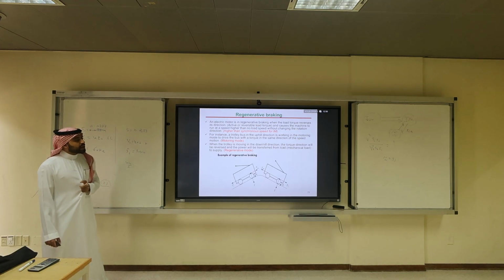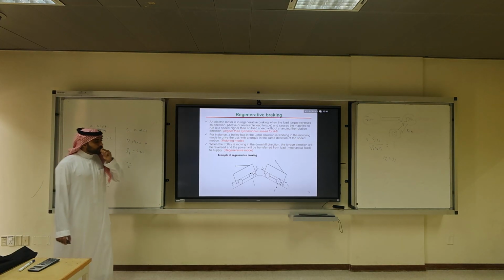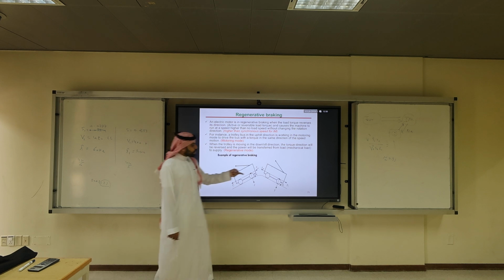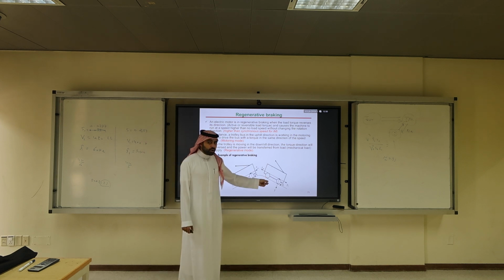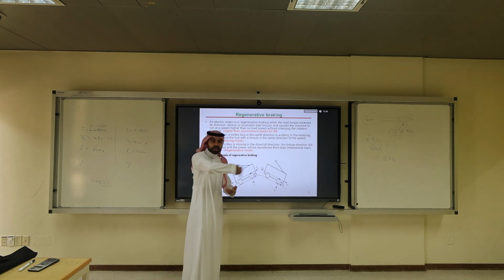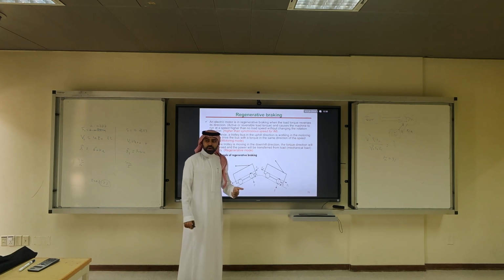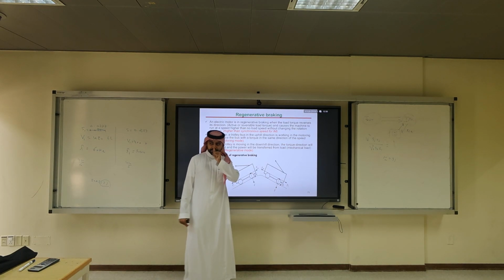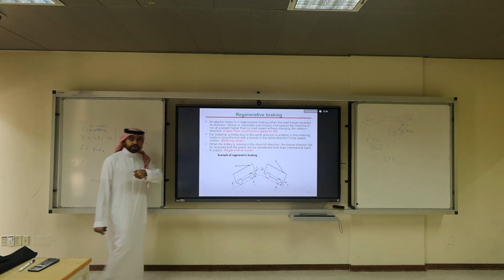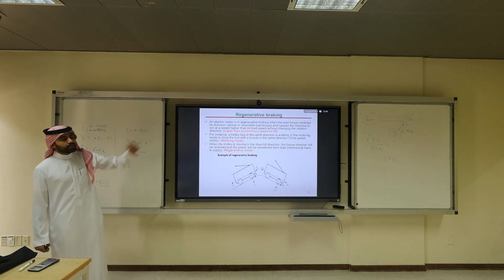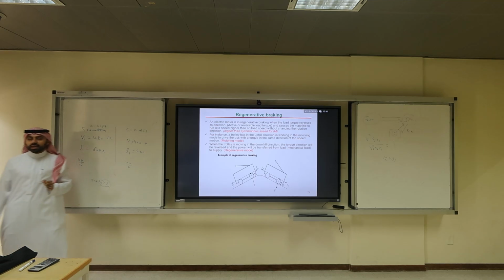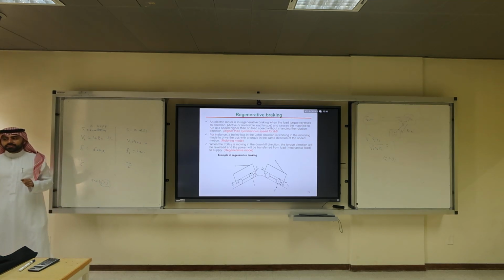Now why do we call it braking? Because if we apply the same torque as the load, our speed will go and become unstable. So we're braking, we're maintaining a speed that is omega. And we are using the flow of energy back to the battery. Is it clear, the regenerative braking? Who doesn't understand? Any question on this slide?